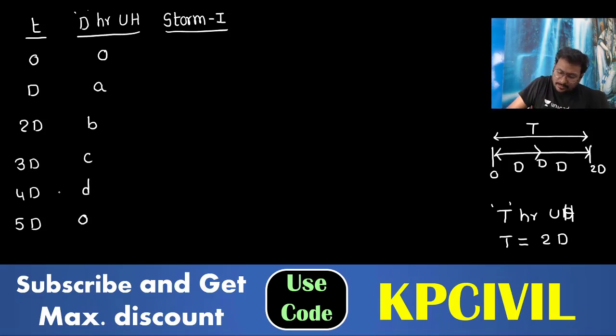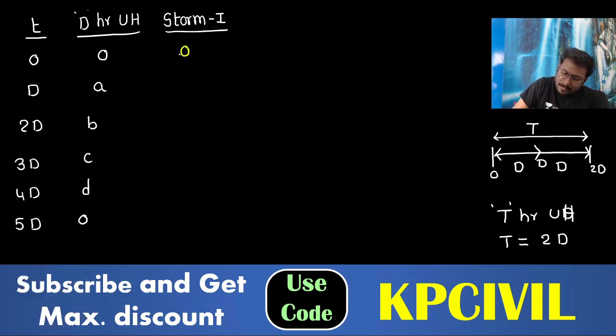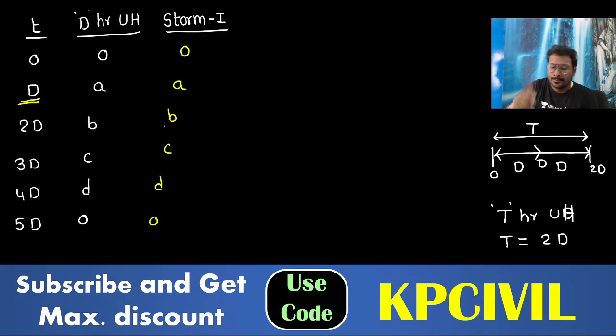Storm 1, 0 to D. So we have started, we are getting the values. Where are you getting the values? Same as it is, copy. No change, because storm 1 ended at D hour. So you are getting the values at D hour: 0, A, B, C, D, 0, no change. You will consider this as it is as the storm 1 unit hydrograph.